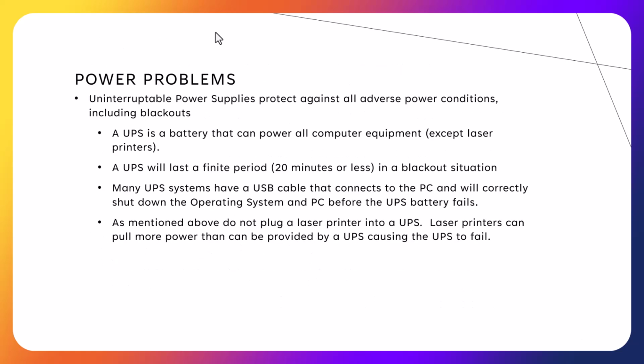An uninterruptible power supply, or UPS, can protect against all of our power conditions, including blackouts. A UPS is a battery that can power all the equipment except for laser printers. Never plug a laser printer into a UPS unless the UPS is rated for a laser printer. A UPS will last a finite period of time, 20 minutes or less, in a blackout situation.